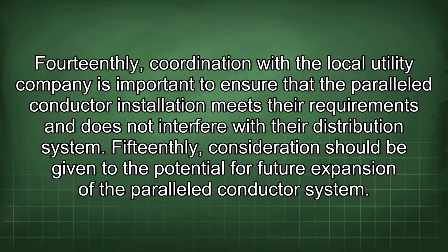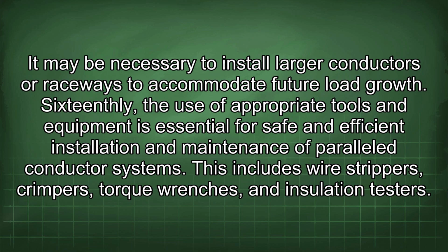Fifteenthly, consideration should be given to the potential for future expansion of the parallel conductor system. It may be necessary to install larger conductors or raceways to accommodate future load growth. Sixteenthly, the use of appropriate tools and equipment is essential for safe and efficient installation and maintenance of parallel conductor systems. This includes wire strippers, crimpers, torque wrenches, and insulation testers.